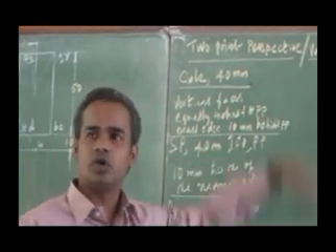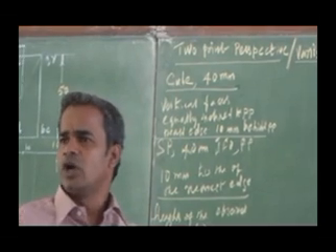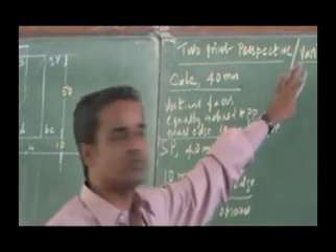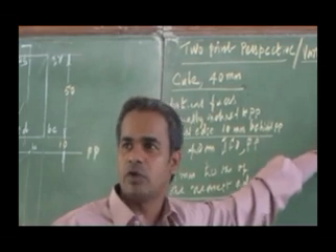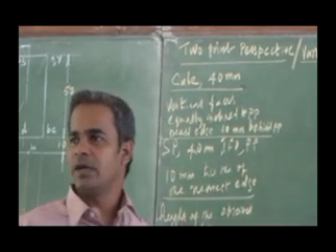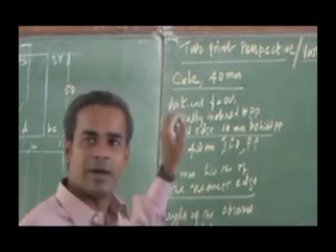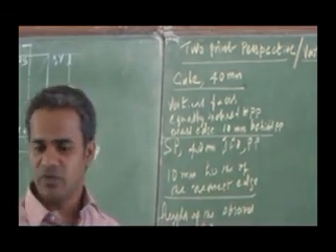So you draw the top view of the cube. No need to draw the front view as we are using the vanishing point method. You draw the top view of the cube, draw the picture plane, ground plane, horizontal plane, and mark the station point. Make it fast. You don't draw the front view here.